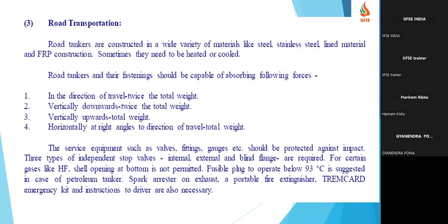So the tanker should be strong, should not leak, and should not destroy itself. Road tankers are constructed in a wide variety of materials like steel, stainless steel, lined materials, and also FRP, fiber reinforced plastic. Thank God, first time I was able to recall this full form in one shot. Sometimes they need to be heated and cooled. So based on the type of chemical, we choose the road tanker, I mean the MOC, material of construction of the tanker.